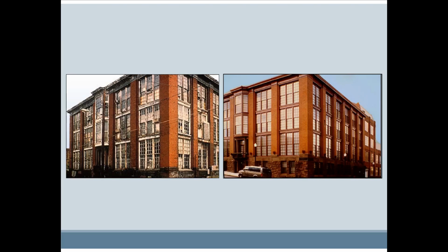Substitute materials can be appropriate or slight variations in details acceptable when it is clear that the visual effect of such change is inconsequential. In the building pictured here, matching aluminum sash with insulated glass and simulated divided lights replaced the historic wood sash. While most window replacement projects involve installation of an entire new window unit, sometimes only the sash must be replaced.